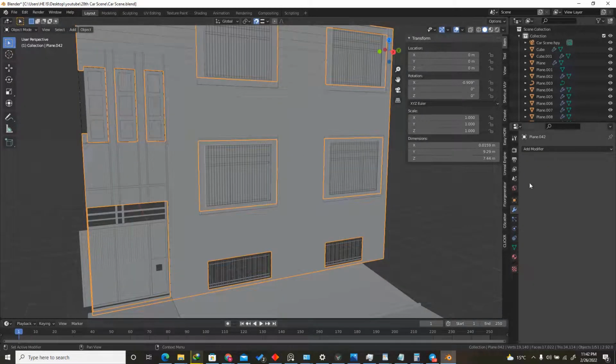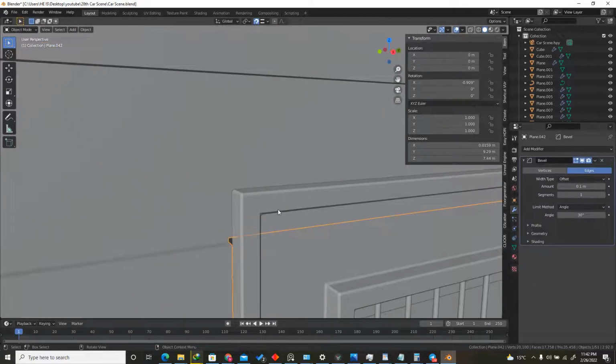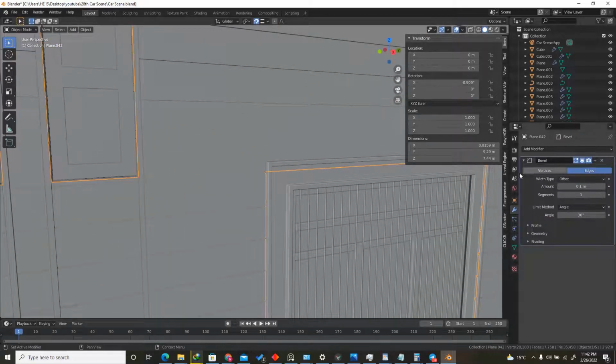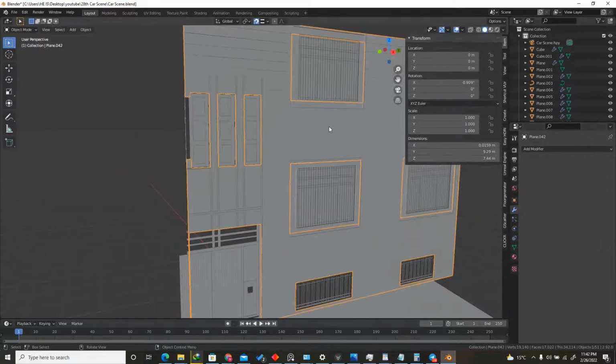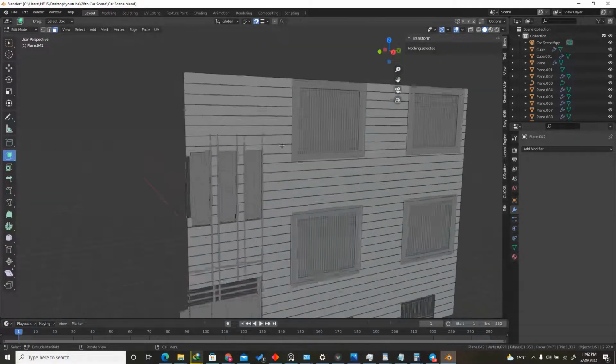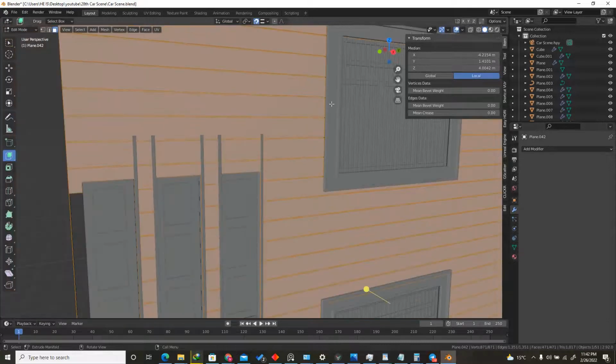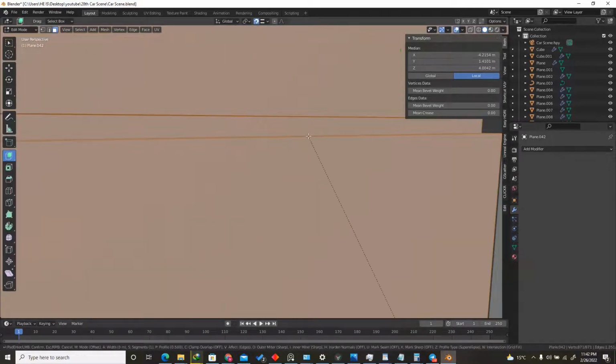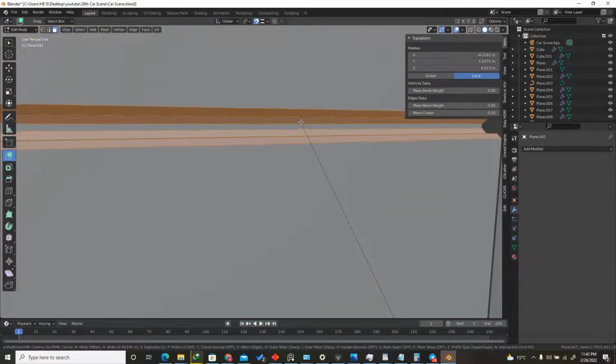And for the wall, when you apply, for example, the bevel modifier, you may not see the bevel being applied. When you have cases like this, you may have to do it manually. So I'm going to delete this one, get inside of edit mode by pressing Tab, press A to select everything, and press Ctrl B, and you can control the bevel like this, as you can see.